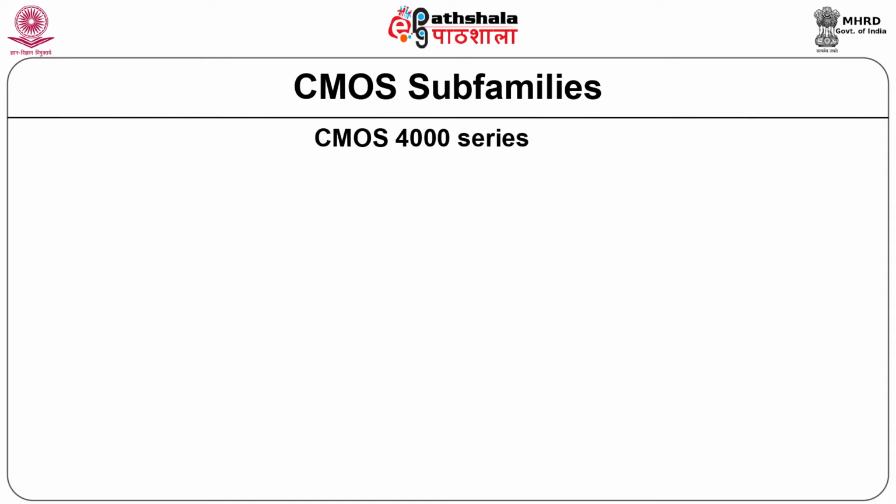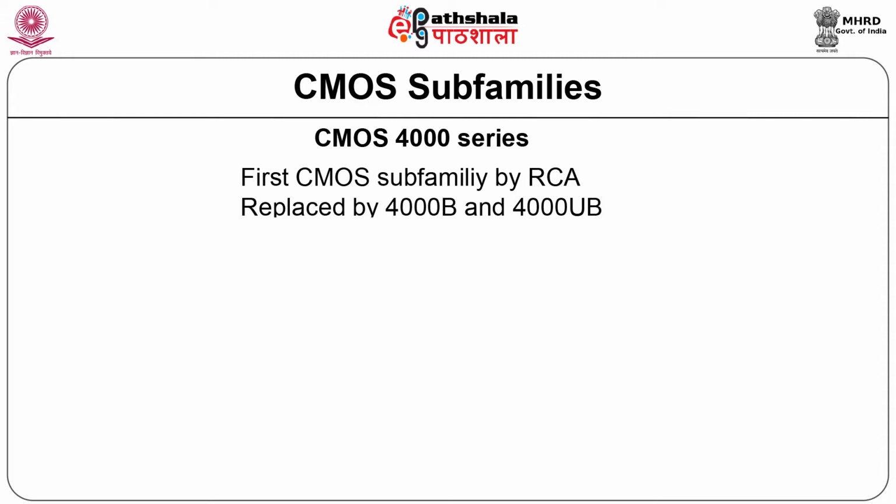Consider the 4000 series. The 4000 series CMOS ICs introduced by RCA were the first to arrive on the scene from the CMOS logic family. The 4000A CMOS subfamily is obsolete now and has been replaced by 4000B and 4000UB subfamilies. We will therefore not discuss it in detail.